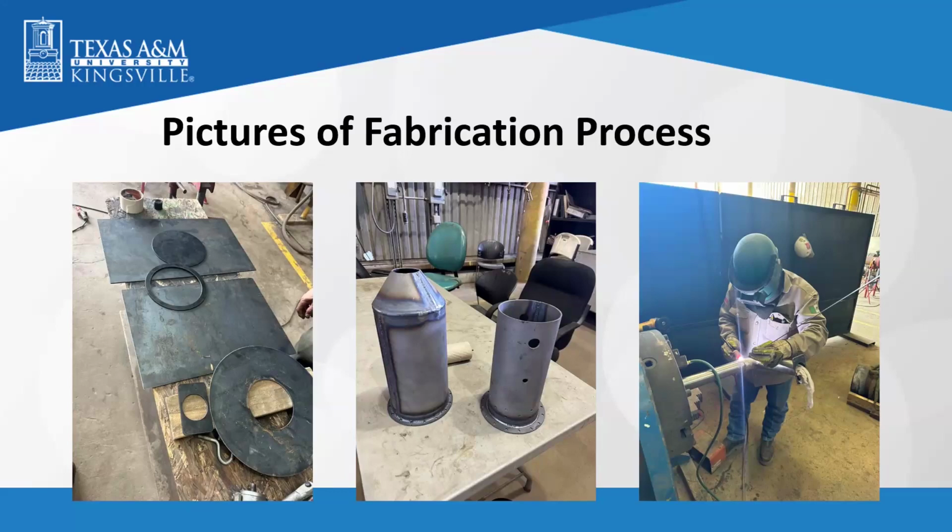I thought the big chamber right there would be that. The chamber is for combustion. Okay, so that's your combustion chamber, but if this is for thrust, wouldn't your exit nozzle be important? Your air goes through here and combusts in here, but simultaneously air is still being pushed through here, which spins this and drives the shaft for your turbo. But talk about your output nozzle, if you're trying to get thrust, isn't the shape of your nozzle an important part of that? I've seen people make an exhaust and I've seen people run them without an exhaust.